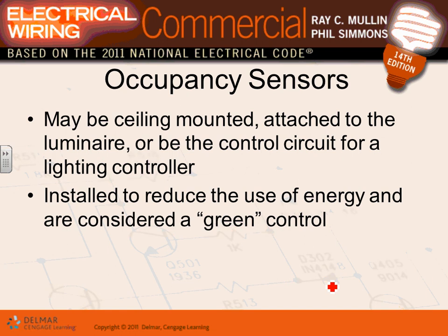Occupancy sensor. With your friend Chad, not next week, the week after, we're going to be talking about lights. You will hear about occupancy sensors. Occupancy sensors are electronic devices that sense your movement. They listen to you and they watch you. They literally have listening ability and watching ability. They sense your presence and keep the light on for 15 minutes, or whatever you set it up for. If nobody moves in that room, they turn the light off. So that's what we do with the occupancy sensors.